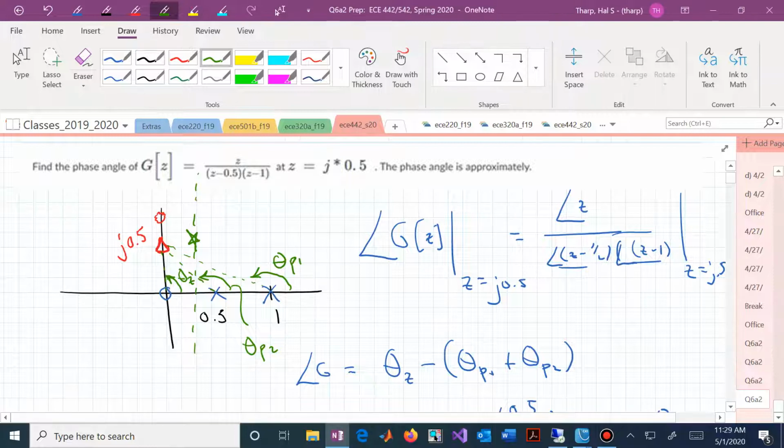Well, now you know that you need to maybe go up here a little bit higher in order to say, that diamond is now where the root locus passes that particular virtual line that we drew. And then you could do a lot of those vertical lines and get these points in the complex Z-plane that have an angle of minus 180. You now connect the dots and you have your root locus. That's another way of thinking about what this root locus diagram is doing.